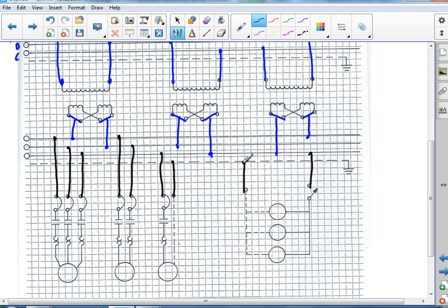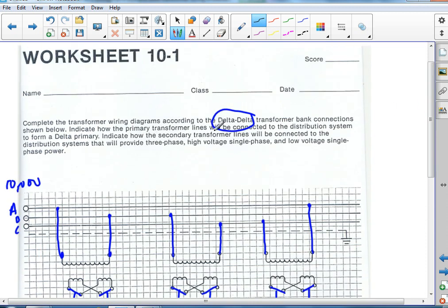But I wouldn't go A, B, C, A, B, A, B, A, B. I wouldn't do that. And the reason is that I have to have the same currents flowing through all three phases. So I want my three phases to be loaded and balanced. If my three phases are not loaded the same, not balanced the same, I'm drawing circulating currents from the power company, which is making the merry-go-round, and they're charging me for it anyway. Okay? And I don't want that. All right, so that was a hookup delta on the transformer.